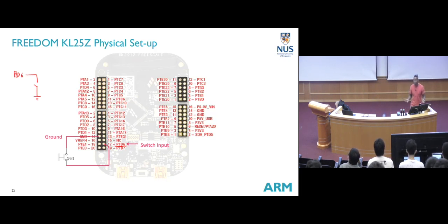It's considered a floating pin. You should never have a floating pin, because if it's floating, it picks up electrostatic signals in the air, and that will trigger a false spike. Yet this is correct. Why is it correct? We will look at it later. It is basically because your controller, which is also available in your UNO, has an internal pull up and pull down. Even though I don't see any resistor, internally I can actually do a pull up.